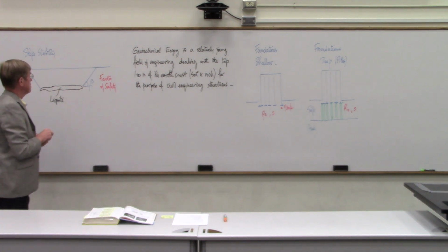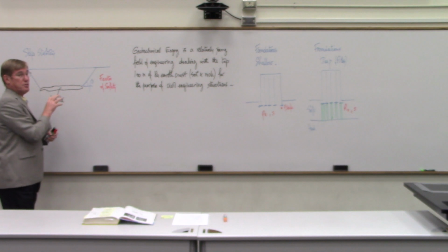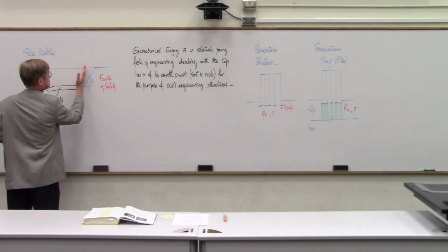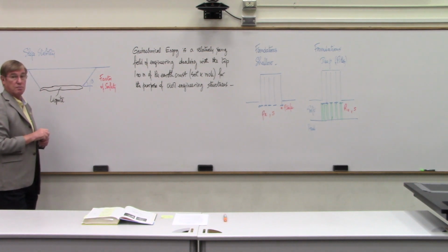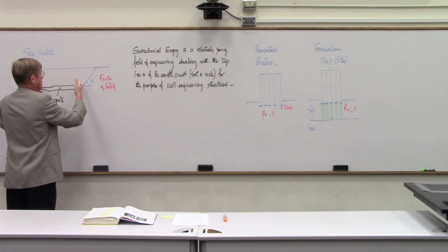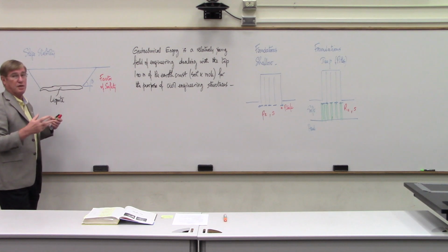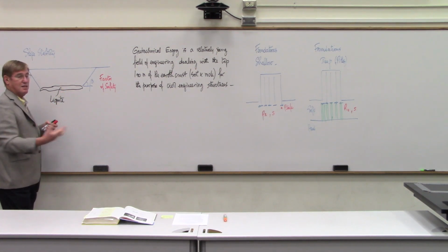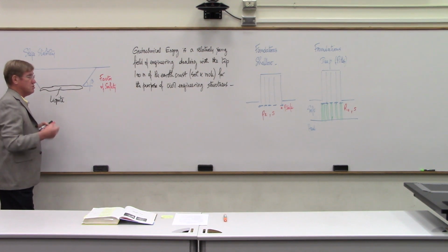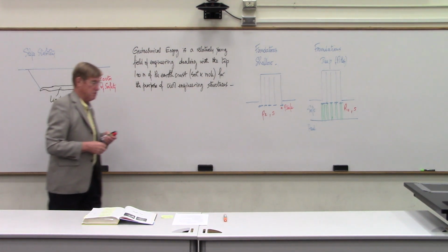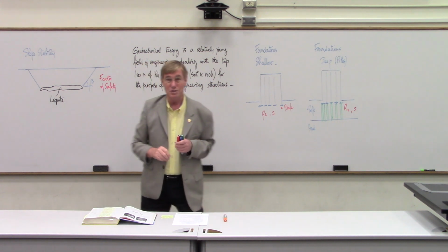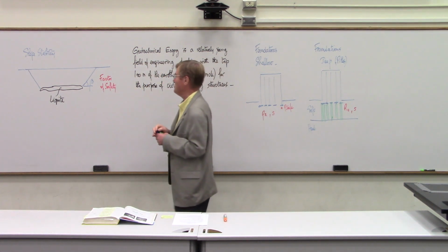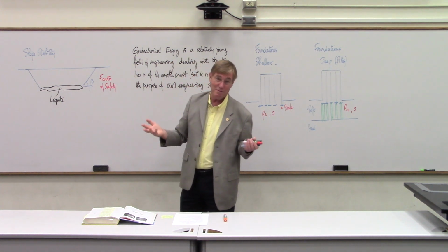And of course, your client, the open pit mine company, or the energy company, wants this angle to be very steep. Because the steeper the angle, the less they have to excavate, the less time, the less money, and therefore the lignite that they get, they're going to be able to sell it and make a bigger profit. So they're pushing the geotechnical engineer to say, no, no, I want to put it straight down. And you say, no, it's not possible. The soil will collapse and you'll have a mess.